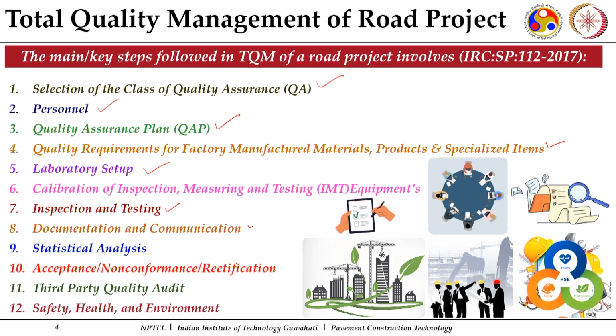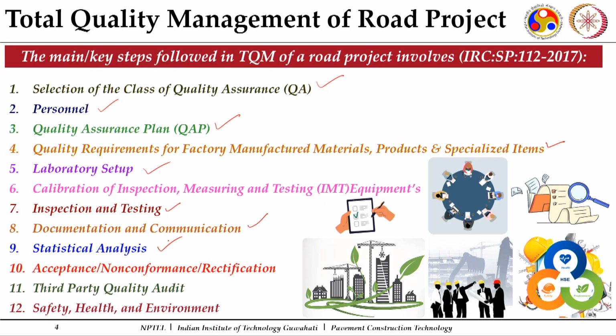All this information needs to be properly documented and communicated well, and circulated as quickly as possible. Thereafter, statistical analysis has to be done on the different results obtained to arrive at a decision, specifically in terms of acceptance, non-conformance and rectification. A third party quality audit may also be done for a particular project, and we need to ensure safety, health and environment during any road construction project. So these were some of the things which were discussed.